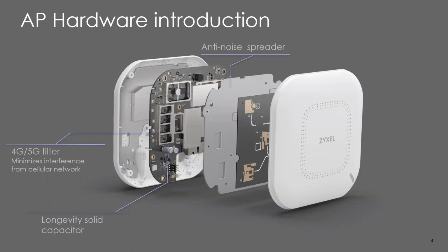So these are solid state products. All of our access points that are part of the SMB lineup, the Flexible or Ultimate Series, come with a lifetime warranty, where a lot of our competition, especially on the lower end models, only comes with a 1 or 2-year warranty. One of the major causes of failure in solid state electronics like this is heat fatigue. Basically, heat builds up over time, and temperatures changing with use can cause solder joints to fail. It can even cause the little switches that are part of your microcontrollers to fail over time.